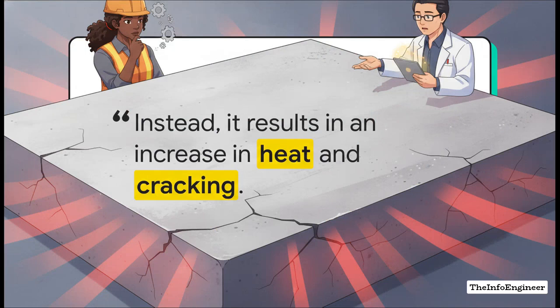Now, what's really fascinating here is how the hard data busts a super persistent industry myth. For decades, those prescriptive specs essentially forced engineers to use high minimum cement contents. But, as concrete expert Dr. Michael Thomas points out, there is a perception that more cement makes better concrete. Instead, it results in an increase in heat and cracking. Right? It's kind of counterintuitive. But those overly prescriptive rules can actually harm the concrete's long-term durability, not to mention drastically inflating its carbon footprint.